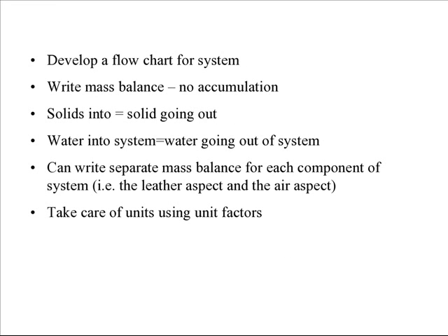Here again we see the different steps for solving these problems. First, develop a flow chart for the system. I suggest you use either of the ones that were provided. Second, write a mass balance with no accumulation.